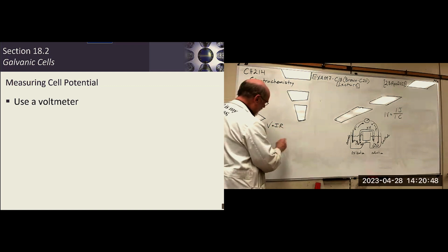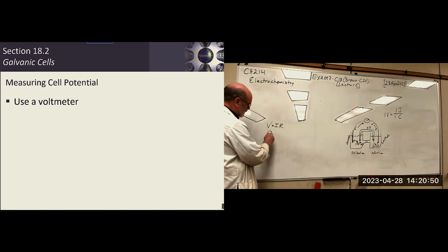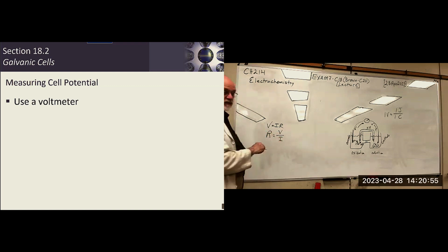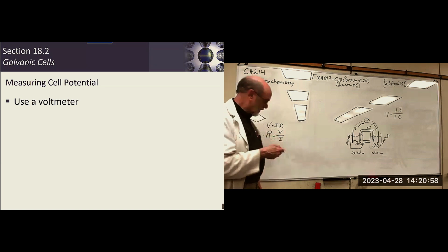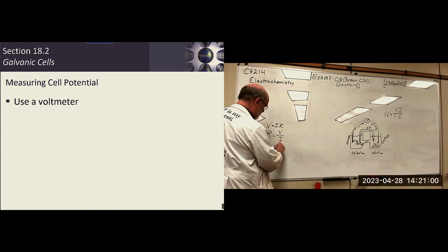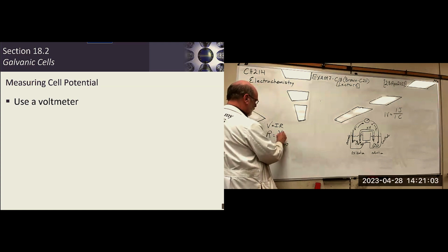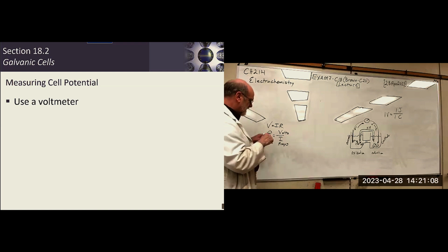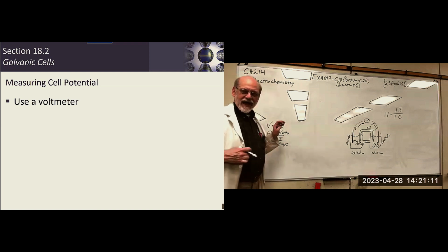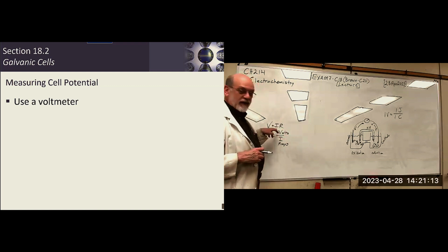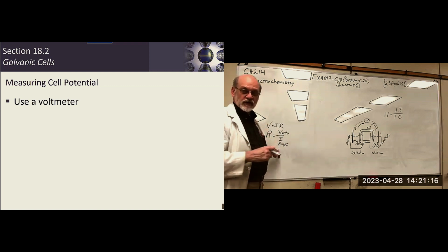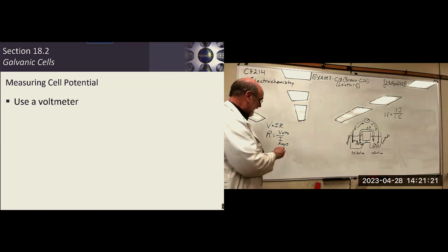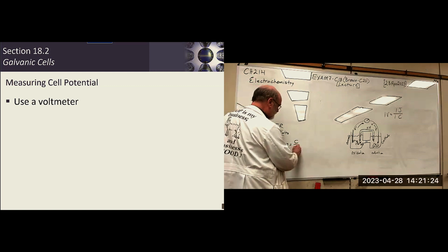R is resistance, and actually the way Ohm wrote it, it was resistance equals voltage per current, and current is in amperage, in amps. So volts per amp is resistance. That just means for any resistor, how much push does it take to get a certain amount of current through that conductor in a given amount of time, because an amp equals 1 coulomb per second.